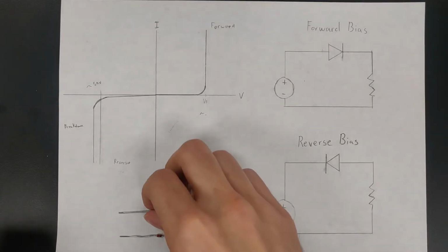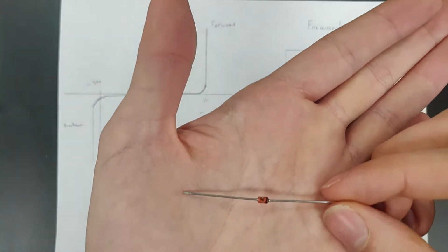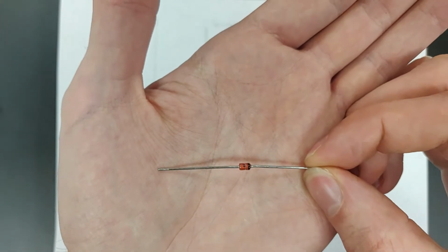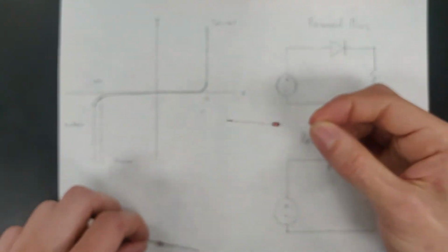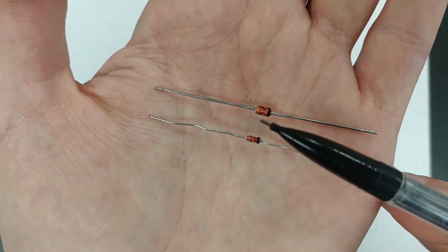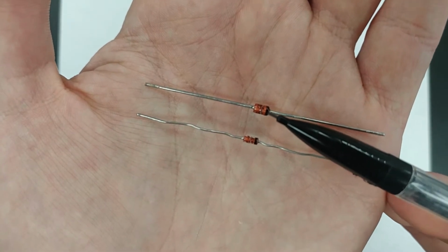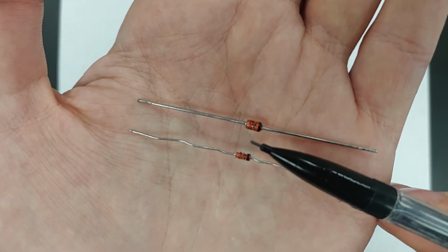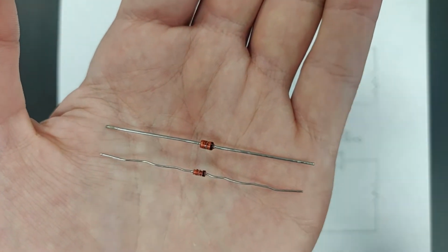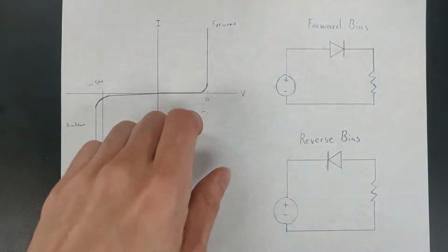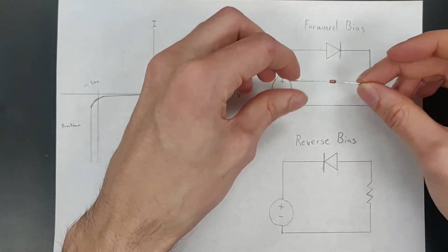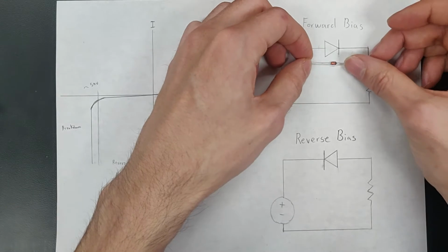The last thing that I wanted to discuss about this component is how you tell the orientation of a diode. If you can see, for both of them, this is the Zener and this is the signal, they have this black line on one side of the diode, and this will indicate what orientation the diode is in relative to our power supply. So let me compare it here to the way it's drawn symbolically.